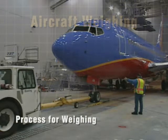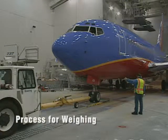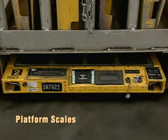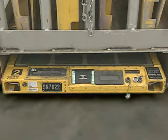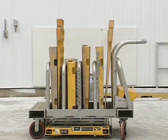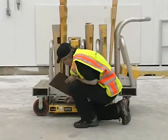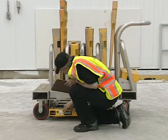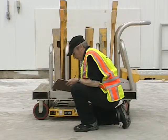With the airplane preparations complete, we are ready to begin weighing. We'll be using platform scales since they are the most common. There are several manufacturers of platform scales. Make sure the ones you use are certified to meet or exceed the requirements of your regulatory agency. Both the Boeing Company and Joint Airworthiness Regulations, or JAROPS, recommend an accuracy of 0.1%. And only use scales whose calibration certification is current.